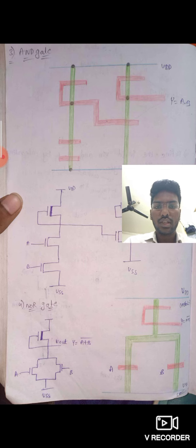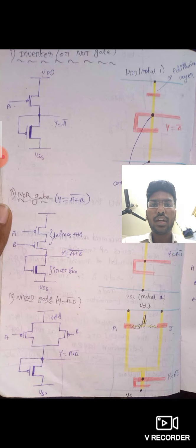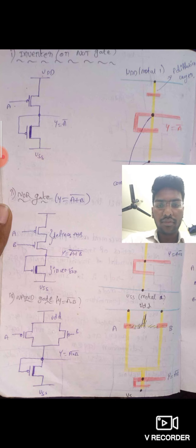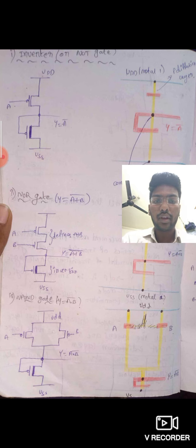To implement this, first we have to draw two metal layers, and then the diffusion layer, and then the polysilicon layer, and at the output we draw the extension to the polysilicon line. Coming to the P diffusion layer, it is similar to NMOS, but in place of green color we take yellow color. The remaining part is the same. But one more thing also changes here. For an AND gate, the gates should be in parallel. For OR gates, the gates should be in series.